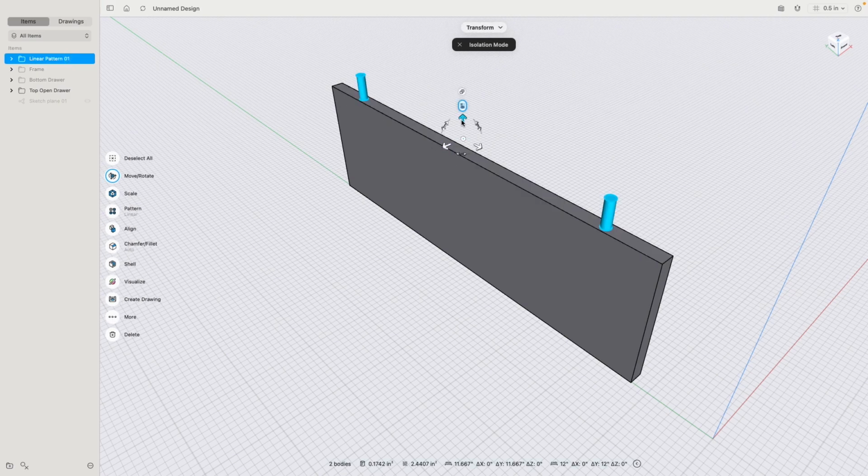This is a 1 inch dowel. It sits on top of it. And it has to go in by 3/4 of an inch, because 1/4 of an inch, it intersects or goes into the top plate. So I click on this up arrow, minus 0.75.